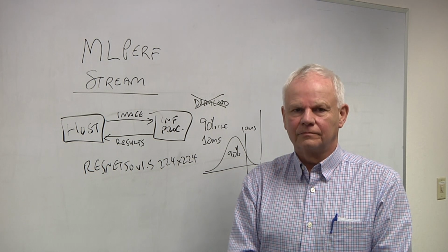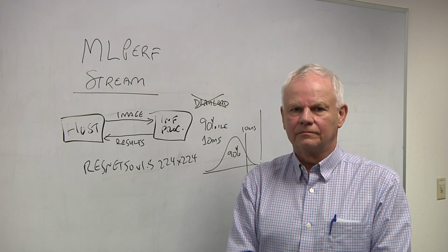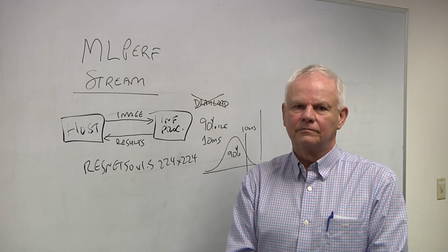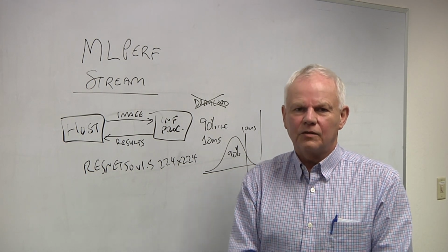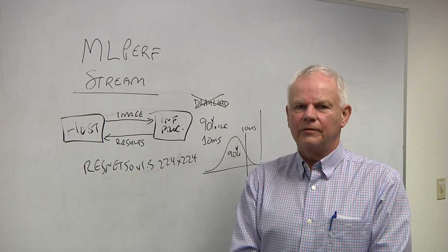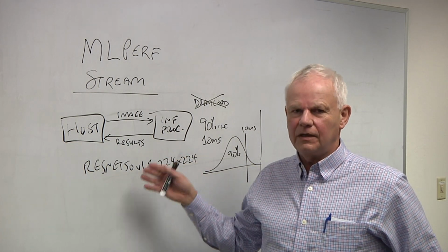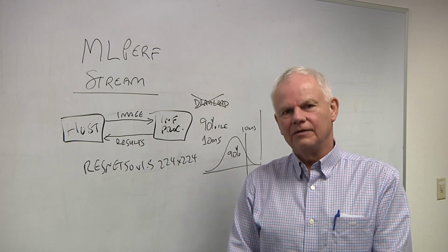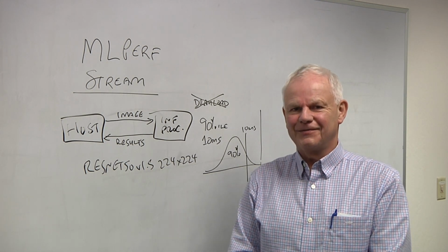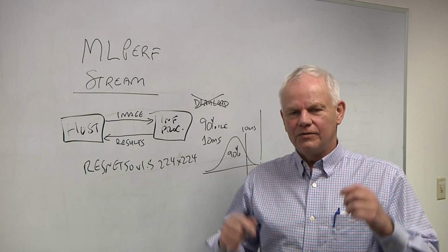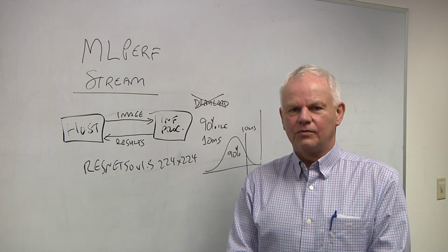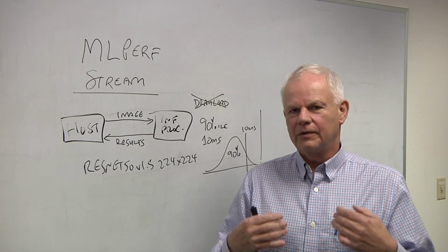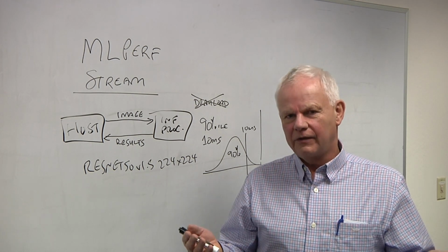You have to calculate that into your benchmarks as well, because it's no longer just a simple this chip versus this chip, it's this chip in this application. And so that's a good point. If you look at some of the chips that were in this study, for example, the NVIDIA Jetson Xavier AGX, it's a very long name. When you dig in, you find out that their module is limited to 90 degrees junction temperature, whereas typically chips in a data center are running at 105.